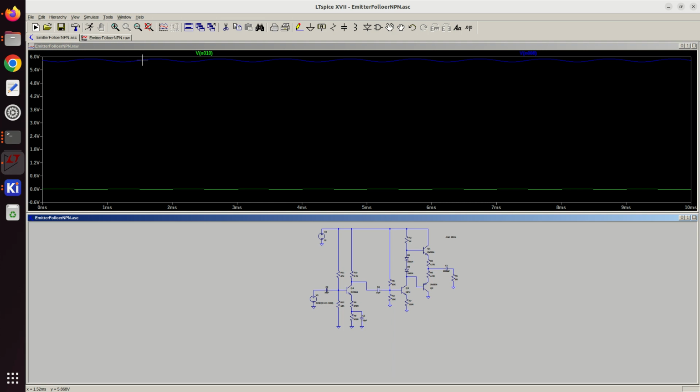It's a lot more. Not exactly sure what it is. We can dig deeper, and finally we look at the output. So the output looks pretty good. What voltage is that? Possibly a quarter of a volt, half a volt peak to peak. So I think we need more gain. So we basically have a gain of 10 here.